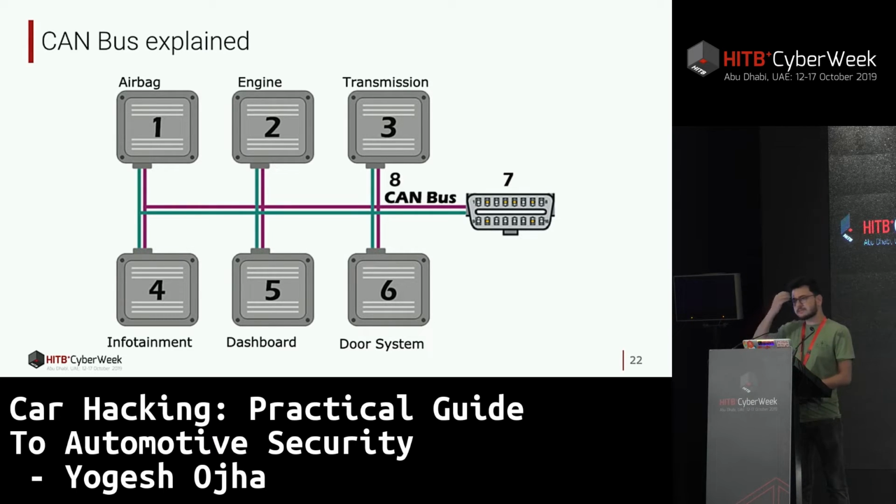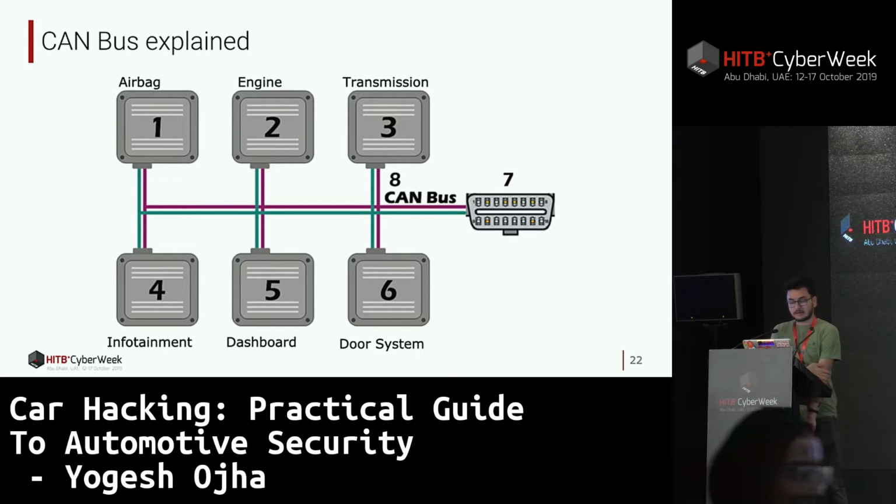If you're sometimes looking for the CAN wires in your car network, there are a few tips for finding the CAN bus. One of the tips is that you can look for twisted pair cables. Generally the CAN bus is going to have just two wires. And if you take out your multimeter and check the voltage, it's going to have 2.5 volts when it is resting. So then this could be a CAN.